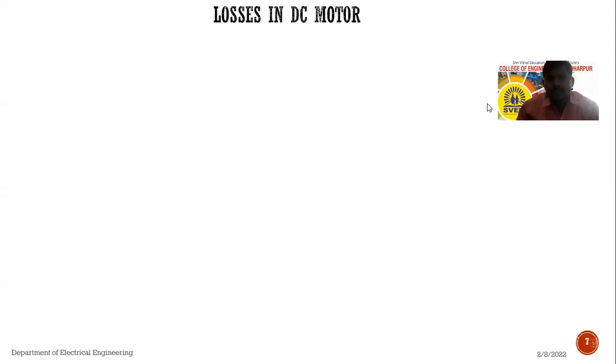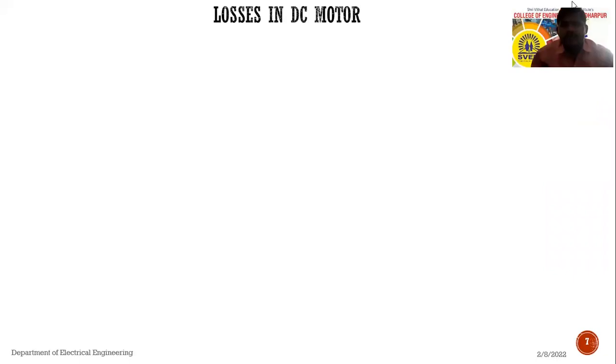In the previous lecture, we discussed the characteristics of the DC motor. We concluded all the characteristics: the torque versus armature current characteristics, the torque versus speed characteristics, that is the speed torque characteristics, and the speed versus armature current characteristics.